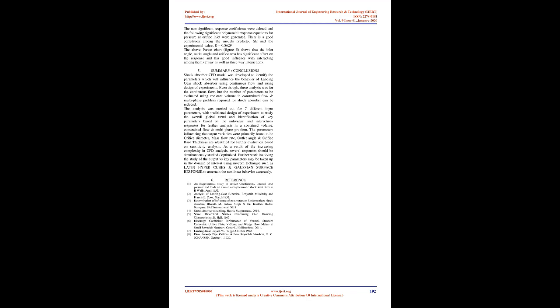5 Summary and conclusions. A shock absorber CFD model was developed to identify the parameters which will influence the behavior of a landing gear shock absorber using continuous flow and design of experiments. Even though this analysis was for continuous flow, the number of parameters to be evaluated using constant volume, constrained flow and the multi-phase problem required for the shock absorber can be reduced. The analysis was carried out for 7 different input parameters, with traditional design of experiments to study the overall global trend and identify key parameters based on the individual and interaction responses for further analysis in a contained volume, constrained flow and multi-phase problem.